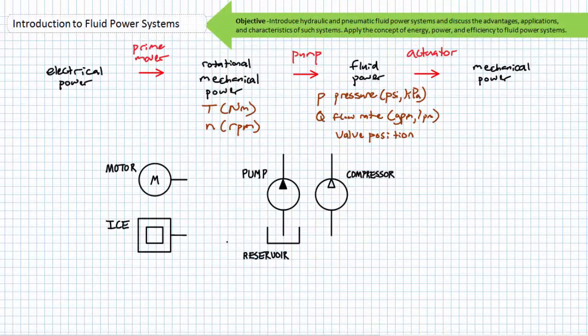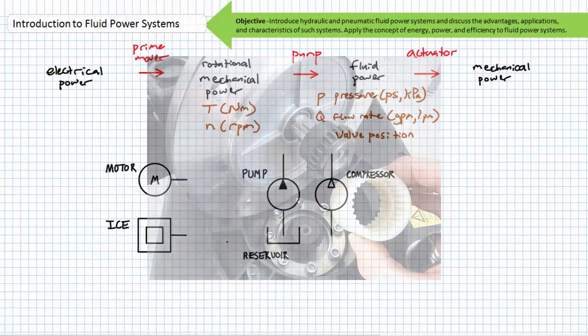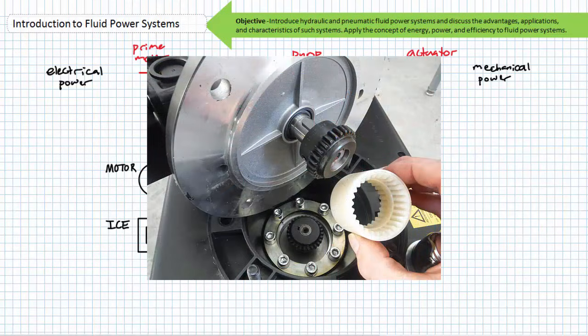Sometimes the fluid power schematic may include the motor and shaft linked to the pump. Electric motors are often illustrated as an M in a circle. Internal combustion engines are often illustrated as a box inside a box. Both motors and internal combustion engines can be considered prime movers. The pump isn't ordinarily directly driven by the prime mover, but rather the two shafts are linked via a coupling. The coupling compensates for misalignment and allows a technician to take the pair apart for maintenance and repair purposes.